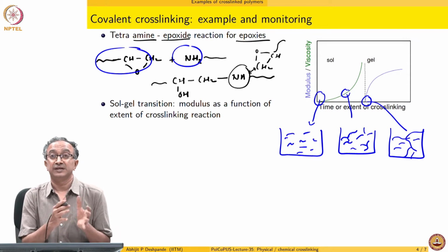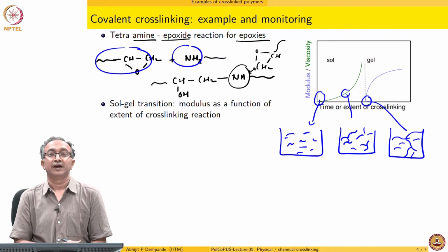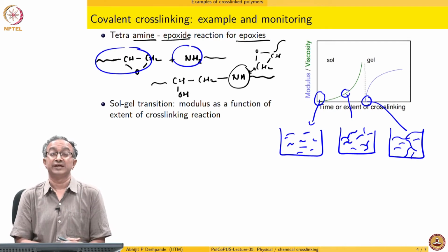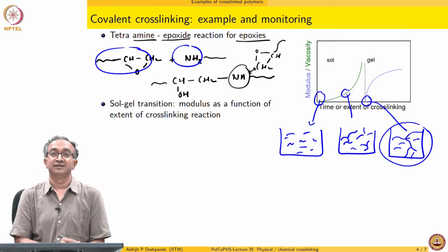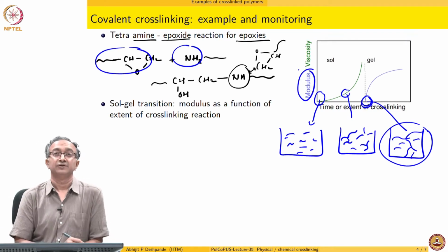As cross-linking happens, you would expect viscosity to increase because molar mass is increasing. And we will discuss this when we look at the rheological response of polymeric systems. But we've already discussed the mechanical properties of the polymer. In the 32 lecture, for example, we looked at stress strain response. And generally, we will not look at stress strain response for a liquid material because they can keep on deforming infinitely. We know that liquids cannot withstand any stress. But if this three-dimensional network is formed, then it can withstand. And that is the point at which, in fact, modulus starts to be non-zero.